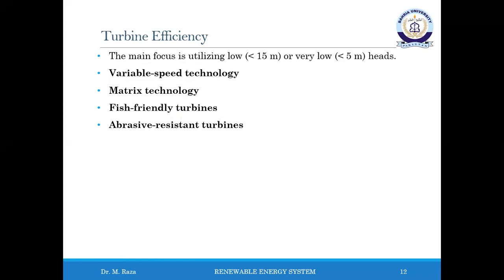If the sediment contains hard minerals such as quartz, guide vanes, runners, and other steel parts are subjected to high scratches, thereby rapidly reducing efficiency. New solutions include coating steel surfaces with hard-wearing ceramic top layers, and are included in this type of research.